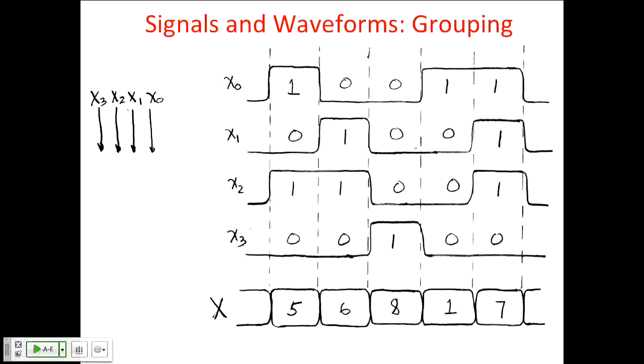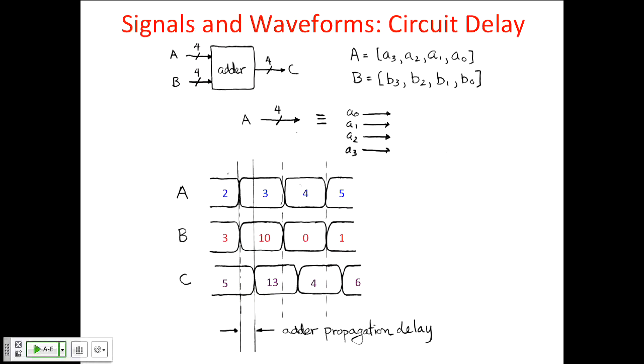And so over time, we have signals traveling together like this. And as I said, there's always a delay when you go through these circuit blocks. So when you go through some logic gates, it takes some time from when that control input is applied to when the output changes to the right value. Okay, and so you apply the input signals and you hold them steady. And while you hold the input steady, the output voltage will settle to the correct 0 or 1 value. When you change an input, for example, the output might have to change from a 0 to a 1. That doesn't happen in 0 time. It takes some finite time to charge up or discharge the output node, changing it from a 0 to a 1.